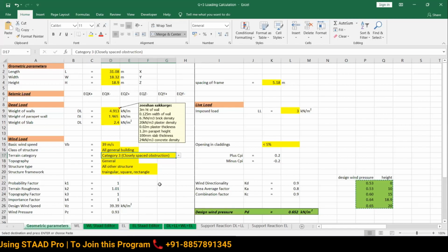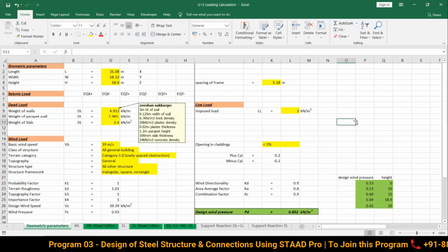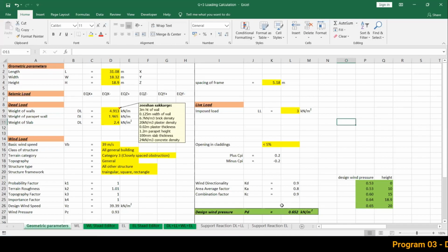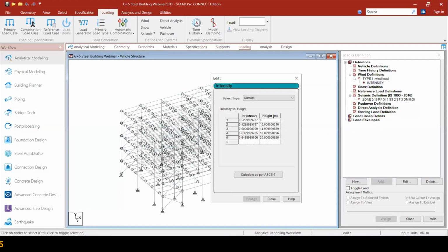That means 0, 10, 15. But in our case, if we model like this, existing 0 is equal to, let's say, 100 MSL, mean sea level. So in that case, we have to define the height as 100, 110, 115 like that. You're saying when we are mentioning height over here, this height should not be from the ground level, but it should be from the mean sea level.